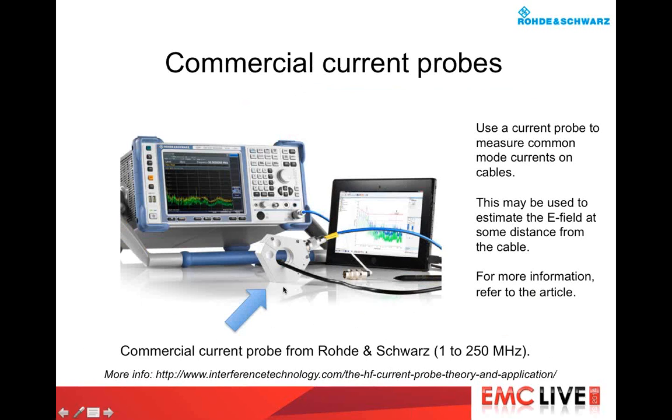Now the other thing we use is current probes. Here's an example from Rohde and Schwarz that will measure frequencies from 1 to 250 megahertz. And again, by knowing what the common mode current is in that cable, you can predict whether your product will pass or fail. That's a very powerful technique.